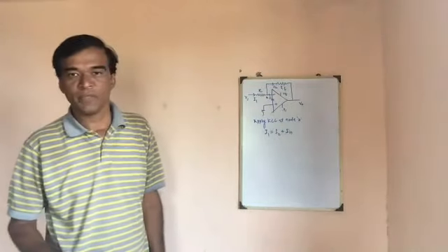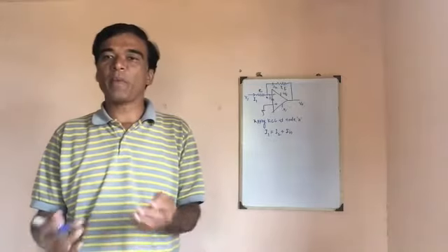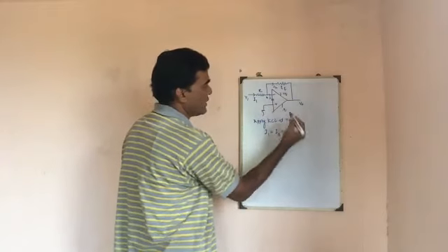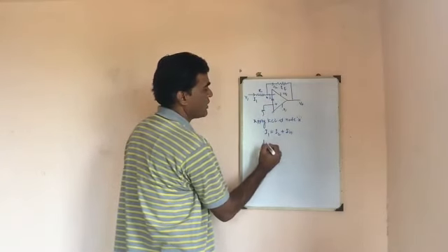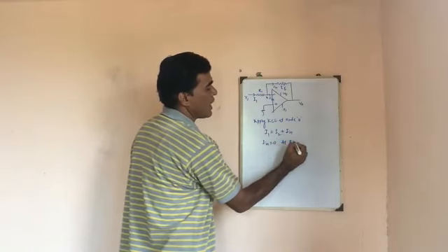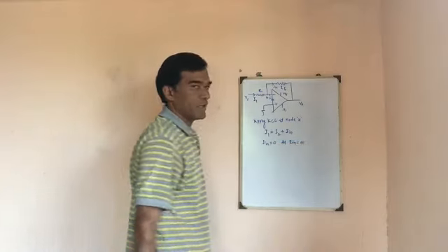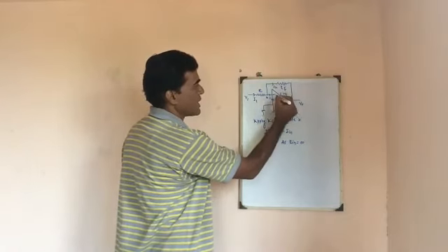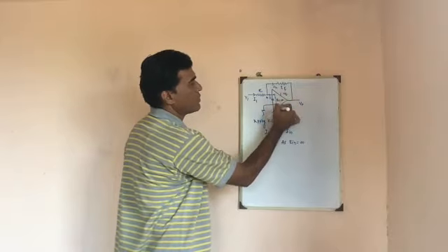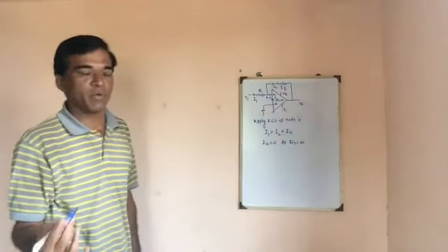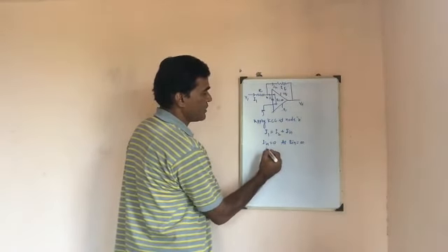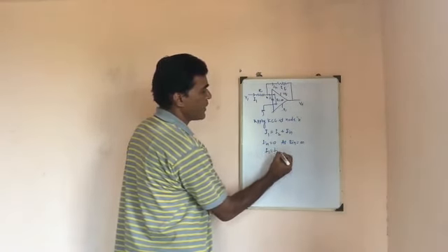As we know, the input impedance of the op-amp is infinity. Therefore Iin comes equal to 0, as Rin is equal to infinity. Is it right? So as Rin is infinity, it acts as an open circuit and Iin will be 0. Now writing this KCL equation, I will get I1 is equal to I2.